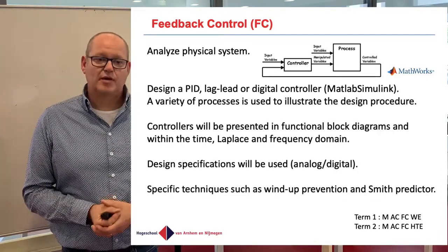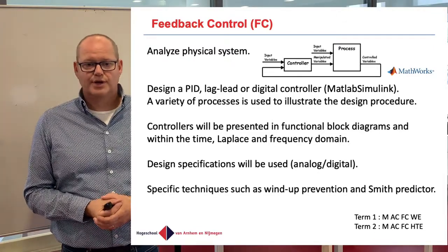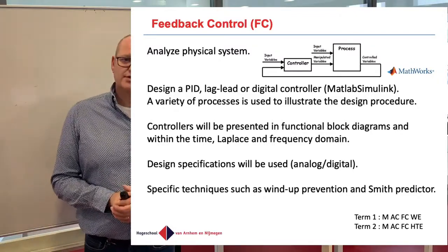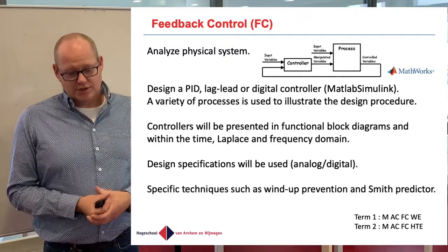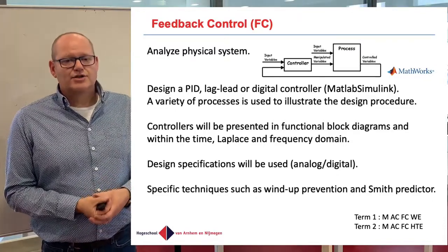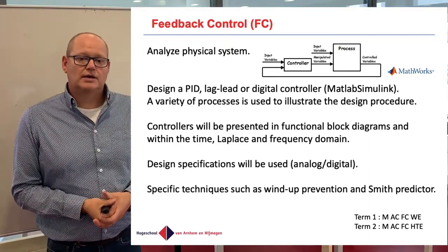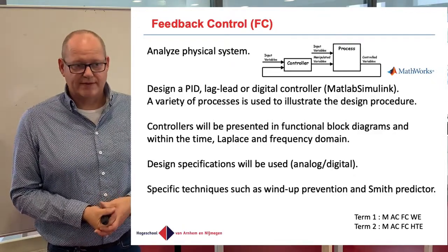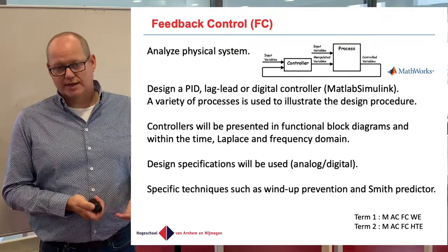So we have a PID classical controller, a lag lead controller, or a digital controller, which you can design. We use some specifications, some design specifications or requirements. Otherwise, we don't have the best controller. And also, at the end of this course, some specific techniques will be taught. Like windup and the solution to prevent that, and also dealing with serious delay times, and we call that using the Smith predictor.